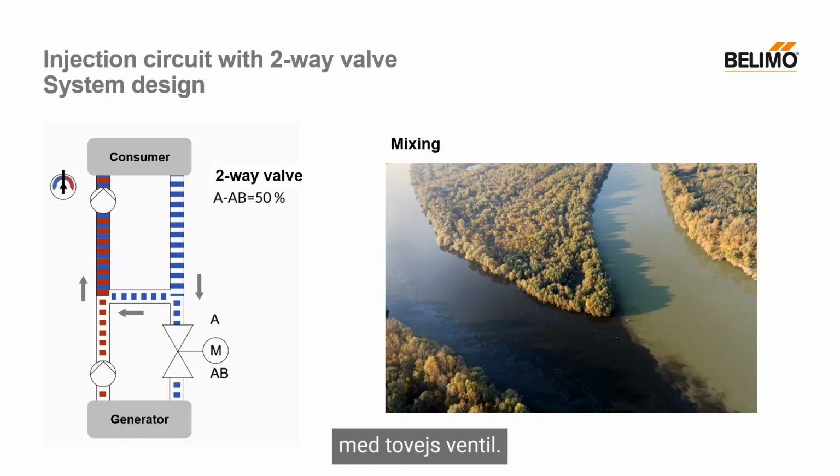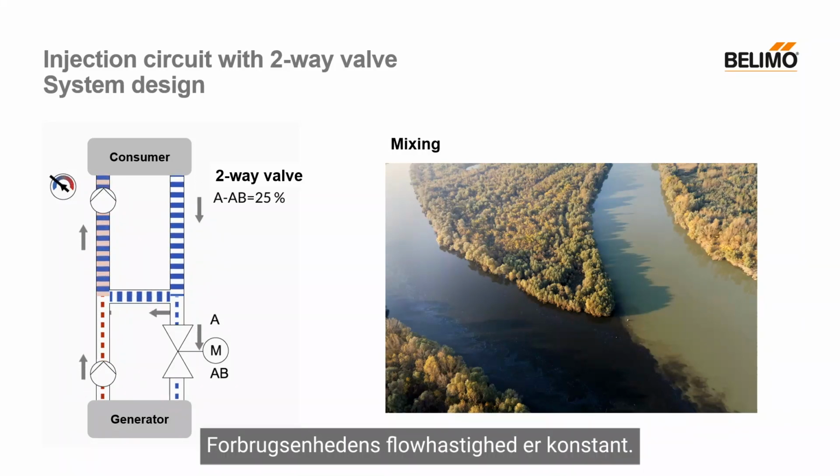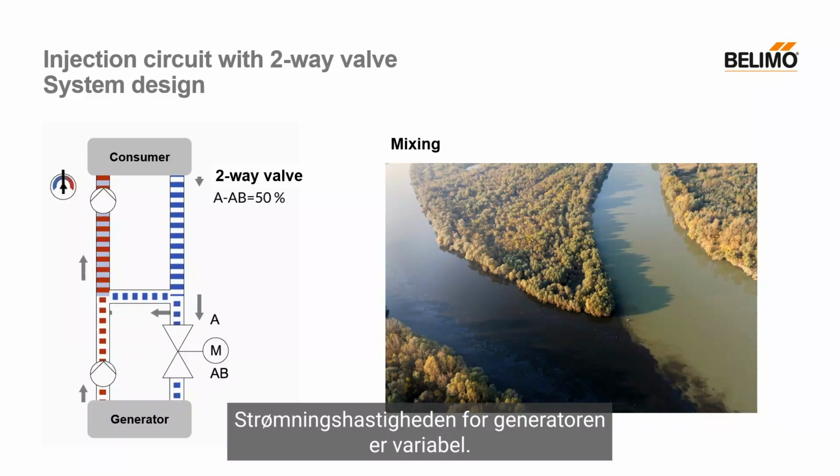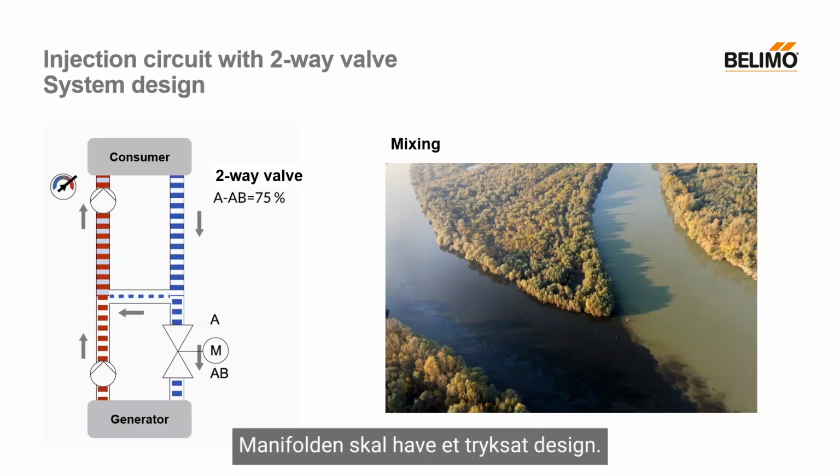Properties of an injection circuit with two-way valve. The flow rate at the consumer is constant. The flow rate at the generator is variable. The manifold must have a pressurized design.